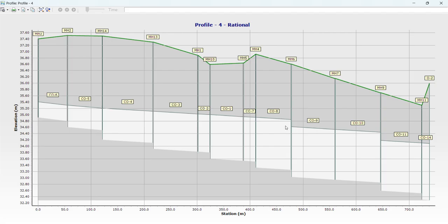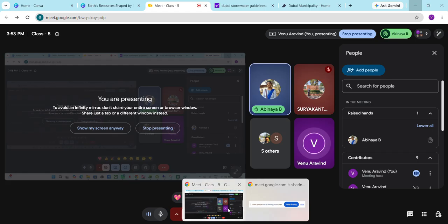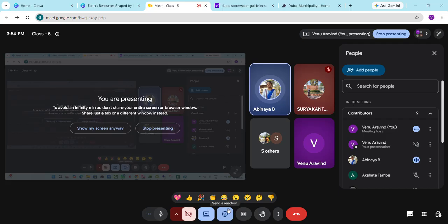We can simply tell, there are multiple steps now. Here one drop, here one drop. From the construction perspective, it will be quite difficult to construct this. If you make a drop here, they will dig until here for the slope of this area, and they will put the pipe and connect it directly to the manholes. Did you get it, Vinay? Yeah, I got that.